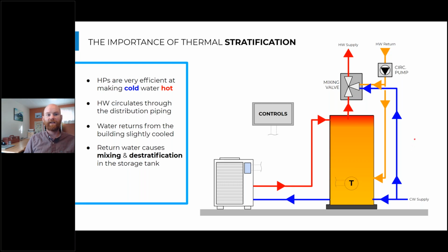So that destratification both reduces the efficiency of our heat pump water heater, it reduces the efficiency of our storage tanks, and can present operational issues or points which are very unstable to operate our heat pump water heaters at. So this is one of the primary design issues with early heat pump water heating technology, and is still a design issue today that we need to address primarily through design and configurations of these heat pump water heating systems.